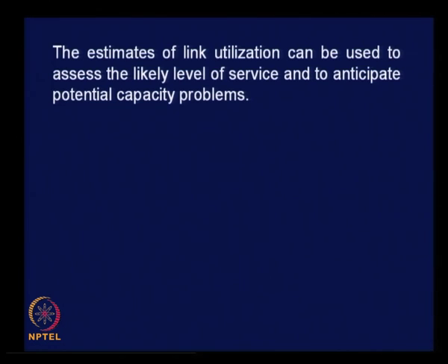After assigning, you will come to know the actual traffic volume on each stretch of a road. Some stretches may be relatively less loaded, that means level of service is better, you can move a little faster. And certain stretches may be heavily loaded, resulting in poor level of service and indicating problem of congestion. All this information you can get after completing the assignment process.